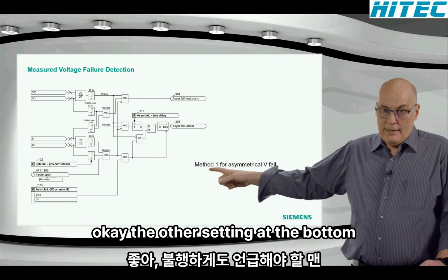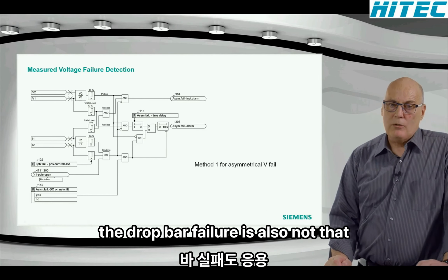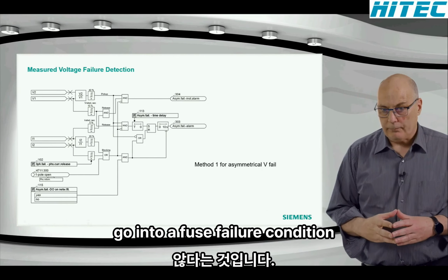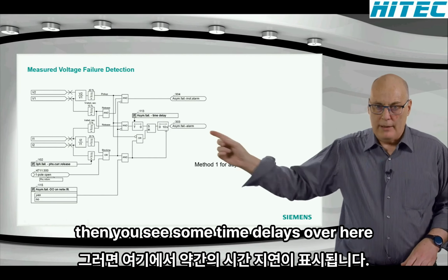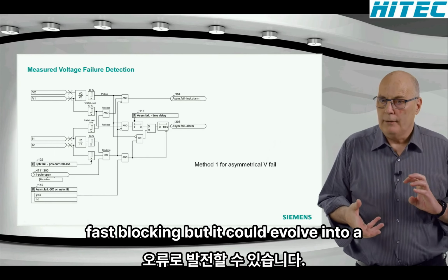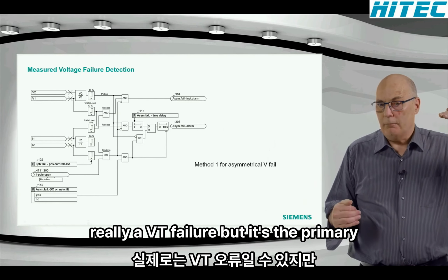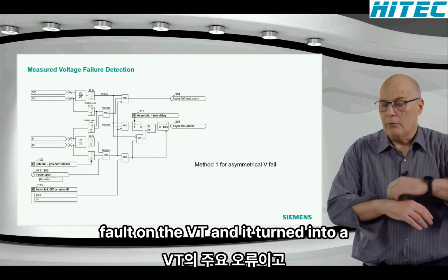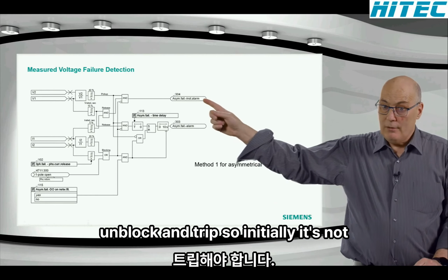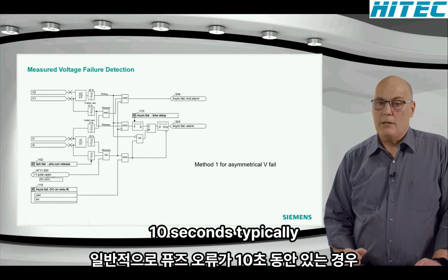Okay. The other setting at the bottom, which I need to mention, unfortunately, the dropout of the failure is also not that clear in application, because if you now go into a fuse failure condition, then you see some time delays over here. Initially, it is a very, very fast blocking, but it could evolve into a fault. Remember, the fuse failure, maybe it is really a VT failure, but it's the primary fault on the VT and it turned into a real short circuit. Then you want to unblock and trip. So initially, it's not latched. Later on, you see there's a flip-flop. It is latched, but that's only after 10 seconds typically.